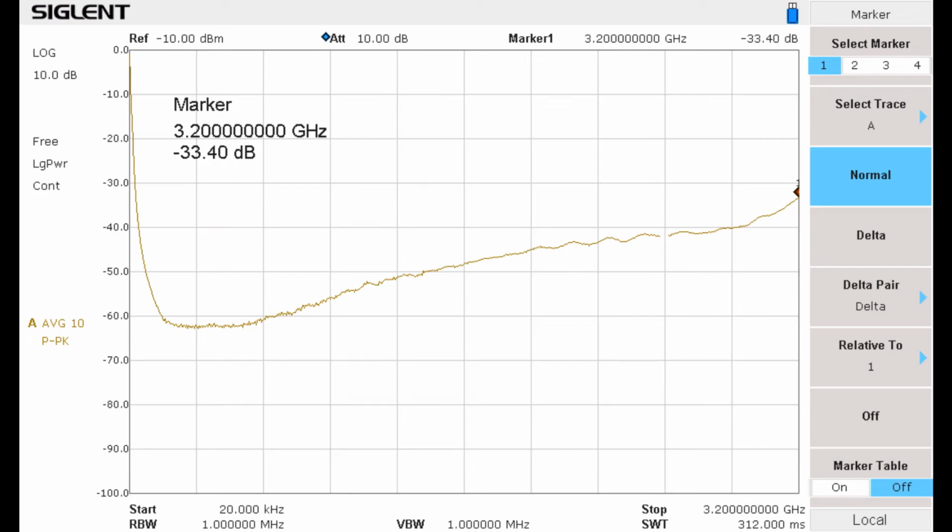So if you want to have attenuation at the very high frequencies, of course what we should have done here is used another device, maybe also from Murata, but specified to have attenuation at a much higher frequency. So it's not that easy to make attenuation at the really high frequencies.